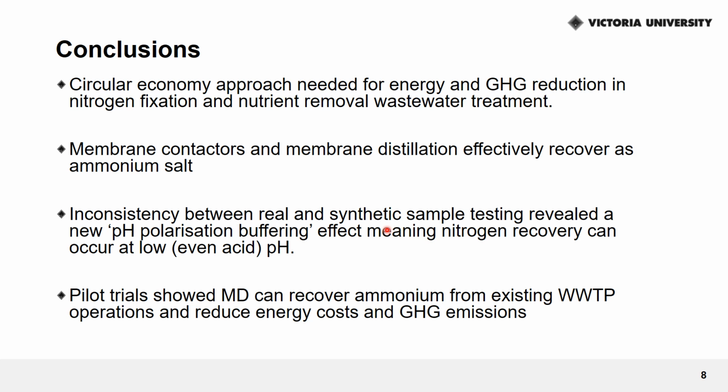When we started looking at this a few years ago, we saw an inconsistency between the real and synthetic samples, which revealed the presence of carbonate, an effect we called pH polarization buffering, which effectively means that the nitrogen recovery can occur even at low acid pHs when carbonate is present, which in most wastewater samples it is.